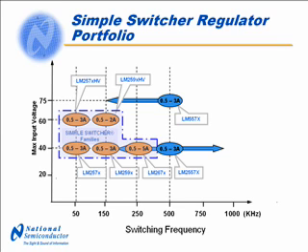The ability to adjust the operating frequency allows the user to trade off solution size and efficiency. 500 kilohertz is shown as a practical maximum for devices rated to 75 volts, while the lower voltage devices can operate from 100 kilohertz to 1 megahertz.